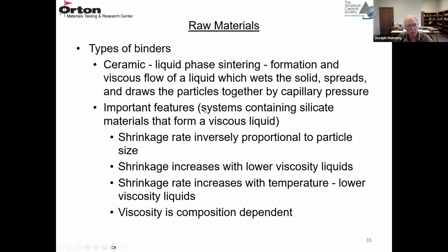So some important features of liquid phase sintering. Again, it's usually going to be a silicate glass that forms a viscous fluid. The sintering rate is inversely proportional to particle size. So again, the finer the particle size, the higher the densification rate. The lower the viscosity of the liquid, the higher the shrinkage rates. The shrinkage rates again increase with temperature because the viscosity of the liquid is going to decrease. And you can control or try to control the viscosity of the liquid by controlling its composition.